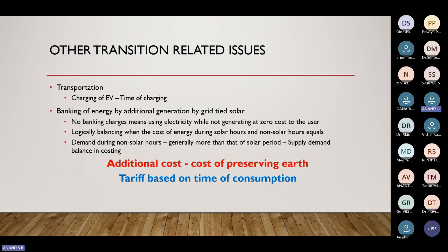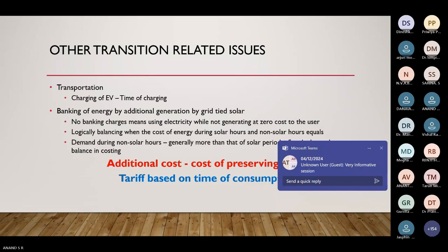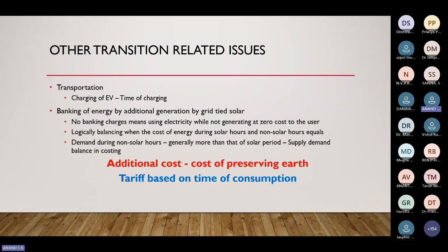Energy meter readings are taken at the consumer level, and that information is going to the consumer through the smart meter basically, and that price of energy can be taken for automatic control of other equipment. If it is a washing machine, it can be planned to be started at say 12 noon, so that if the price of energy at that time is much less, it can be made use of.